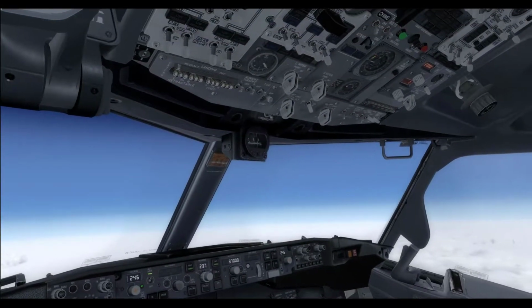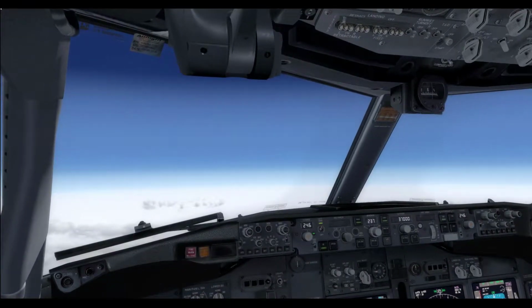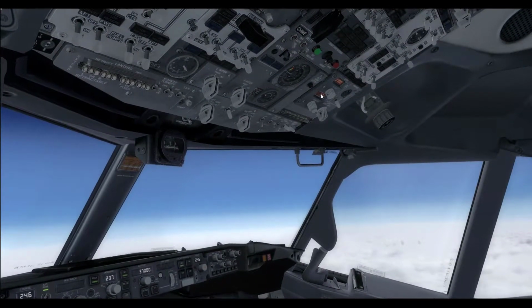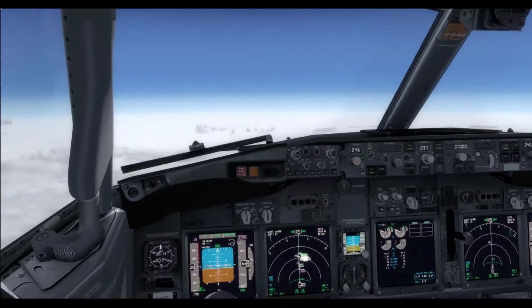We're already prepared for approach. The landing altitude is missing, so you take a look at the charts and you look at the bottom left corner at the top. Aerodrome elevation 157 feet. Round that up or down? In this case, down: 150 feet.